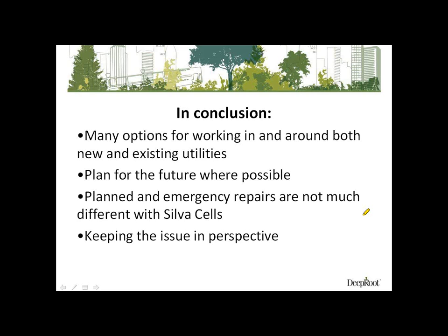Again, as in anything in construction in the ground, compaction is key. Compaction everywhere around. You want to make sure that the geogrid is put in properly. You want to make sure the rock, the stone that gets in there, when you get to the top, gets at least some kind of tamping down on it to make sure that the rock works itself in with each other and gets some aggregate interlock going.